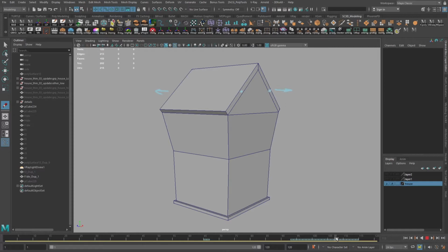Select the side faces of the roof and extrude it. Now select the faces of the roof leading to the bottom and extrude it twice. For the last touch, for the roof tip lines, select the faces and extrude it. Great, we made a shape for a house.